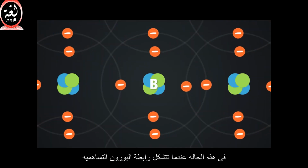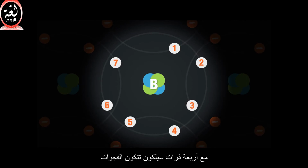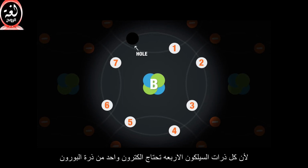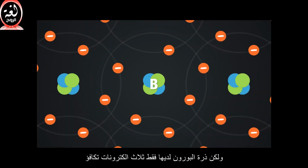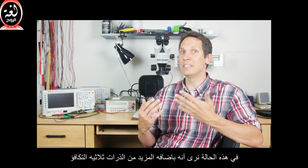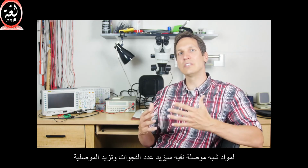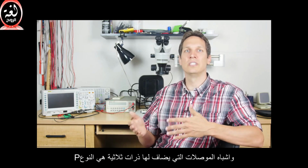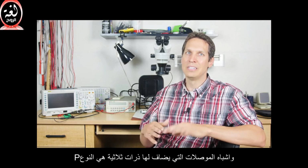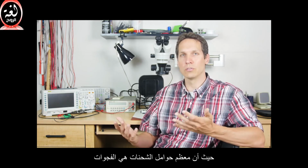In this case, when the boron covalently bonds with the 4 silicon atoms, a hole is produced. This is because each of the 4 silicon atoms requires 1 electron from the boron atom, but it only has 3 valence electrons. In this case, we can say that by adding more trivalent impurity atoms to an intrinsic semiconductor material, it increases the number of holes and improves the conductivity of the semiconductor material. Semiconductors doped with trivalent atoms are p-type semiconductors, since the majority of its current carriers are holes.